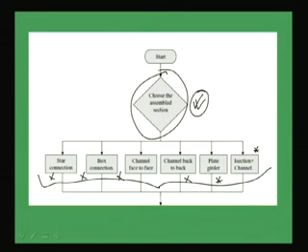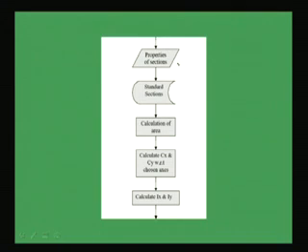So what will be the equivalent cross sectional area and other properties of the built up section, that can be found from the software very easily. So in the algorithm, first we will give the option to the user on what type of section he wants, whether star connection or box connection, channel face to face, whatever he wants, he can first choose that. Then they will find the properties of the standard section, means properties of the individual sections. This is given in the IS, means SP6 1962, this IS handbook, from where they can find the standard sections and their properties.